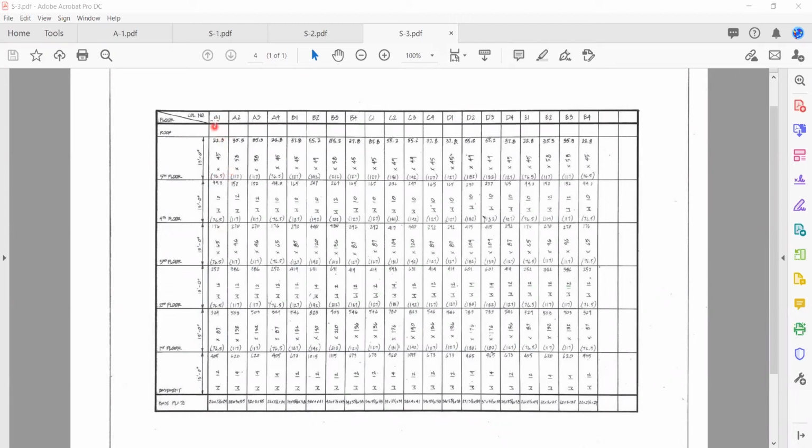So at intersection A1, on the 5th floor to the roof, I have a W member that's noted in this column here. Okay, so W here, this is W18 by 45, and it's going from the 4th floor actually to the roof. So all of these, and in your reading, you will have maybe come across a bit about how high the columns are.